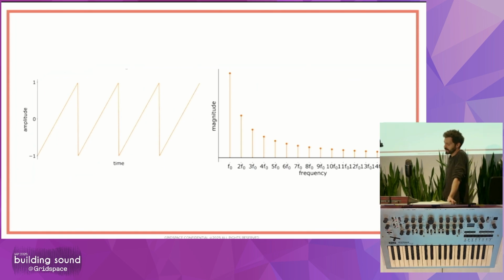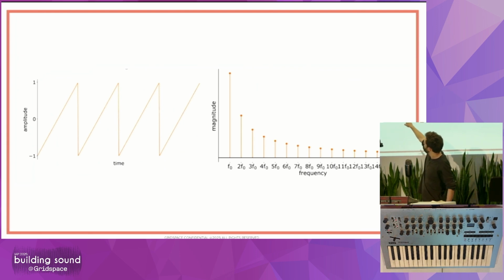if the first oscillator is playing at a frequency that's a little bit lower, then the amplitude's going to go up, go back down to the bottom of its period, and then get maybe halfway up, and then the period of the first oscillator is going to be reached, and it's going to jump back down to the bottom. And so you'll get this alternating pattern of big triangle, little triangle, big triangle, little triangle. And again, that just adds some harmonic richness.